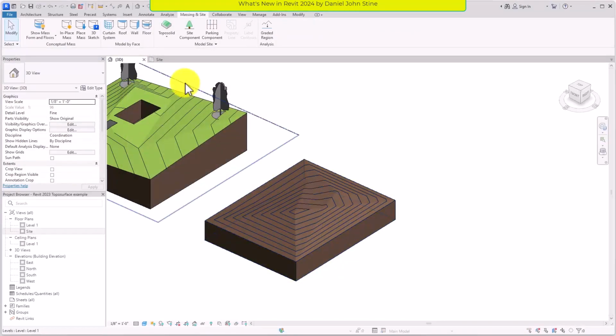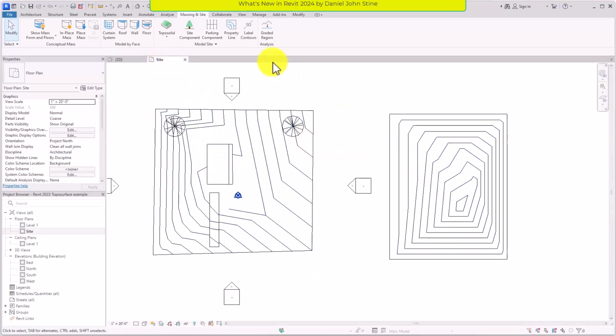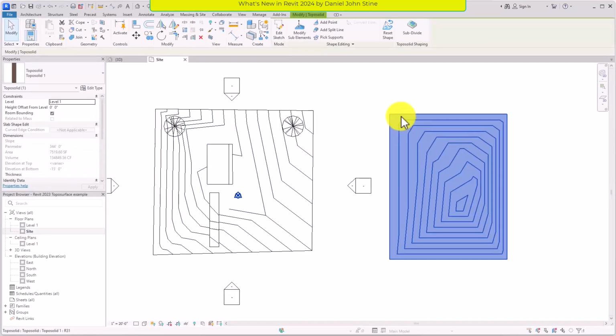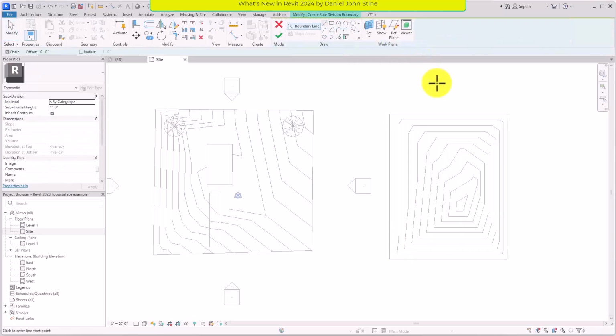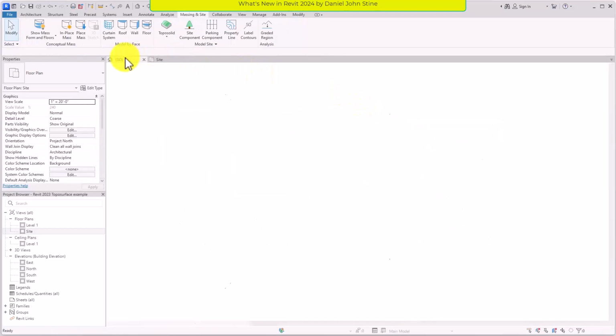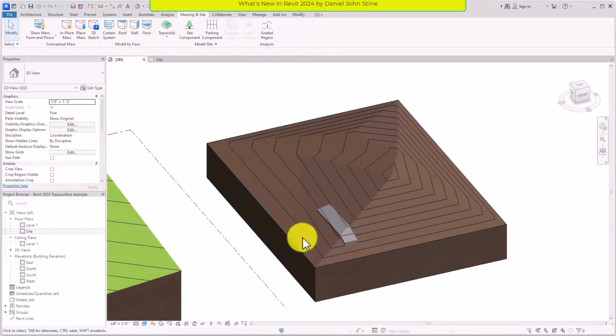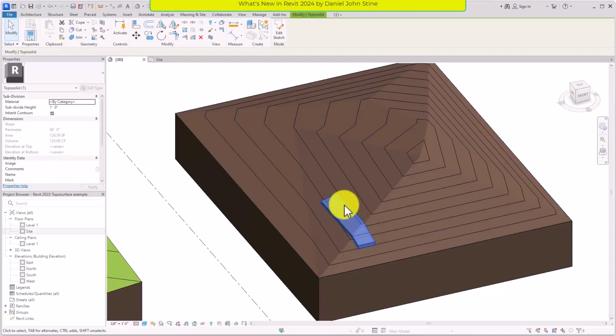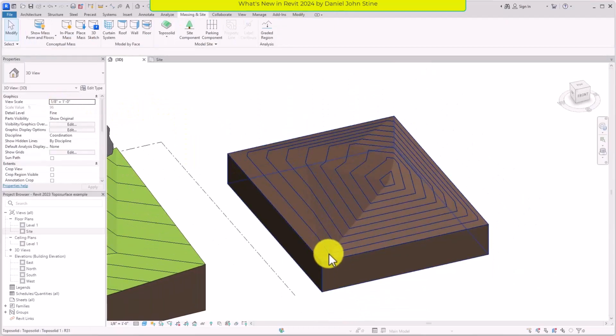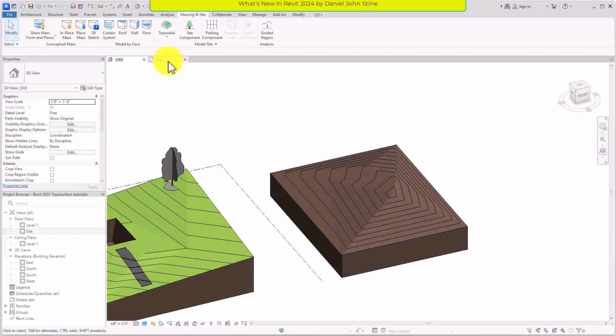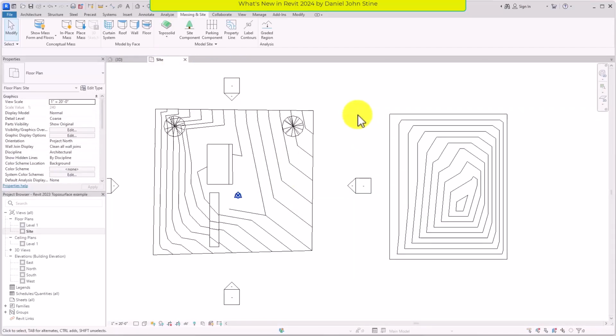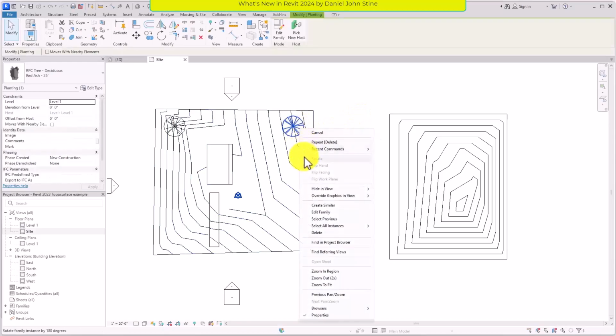And then finally, if we select this first and then go to subdivide, this is where we could add what would be the equivalent of a subregion. And so this can be selected. You can specify a material, a height, and then you could also delete it, just like a subregion. And then after that, of course, the other commands work as normal.